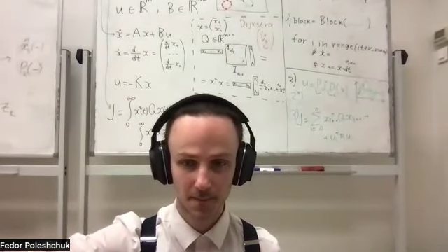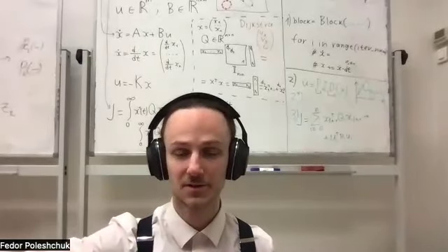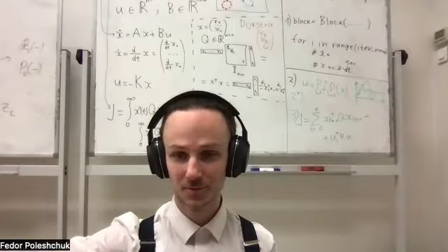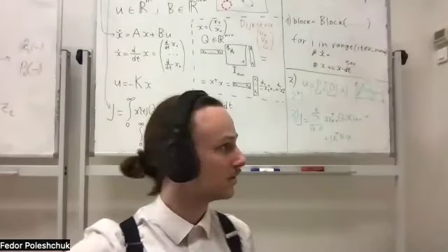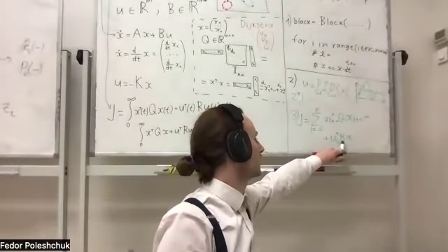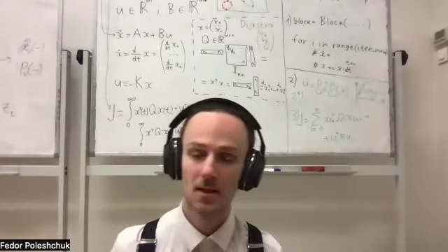So you said set up the Spring Mass simulation, design a controller. Yeah, just a PID controller, and play with the parameters. And then set up cost calculation. Yeah, quadratic cost calculation in this form. So Q will be a 2x2 matrix, R will be a 1x1 matrix, just a scalar.